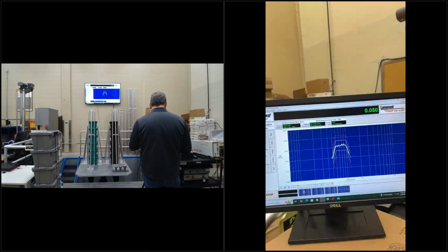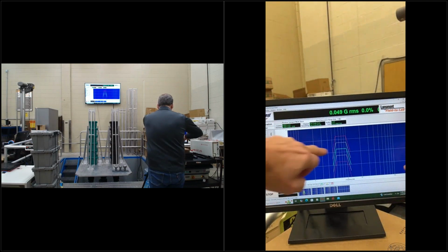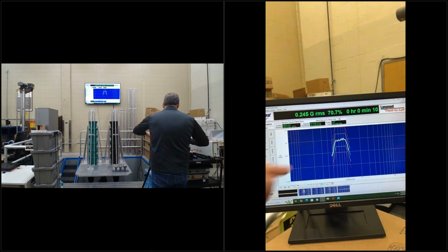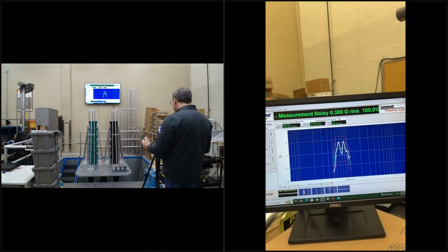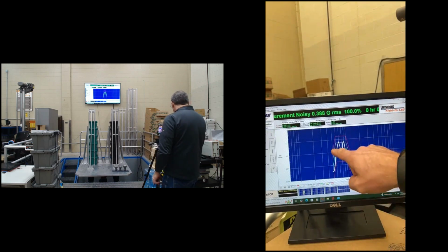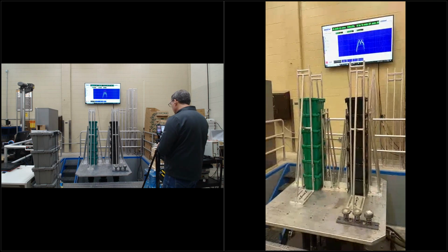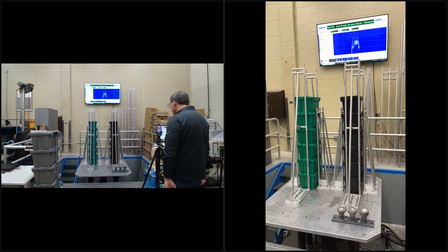And then lastly, a weird looking profile. Get rid of all the noise, or not noise, but the frequency content from 1 hertz to 6 hertz and from 12 hertz to 100 or 200 hertz. Get rid of that. I'm just running a test profile from basically 6 to 10 hertz, driving it hard, still getting that response from my stacks.